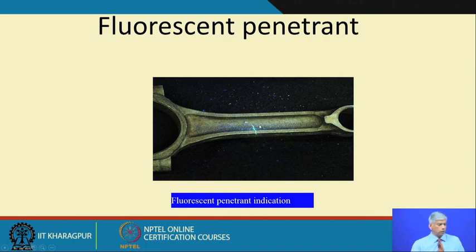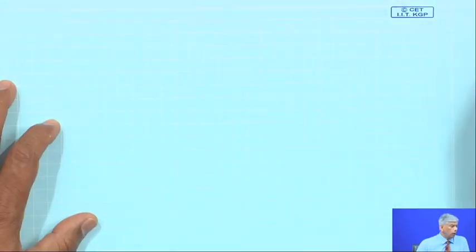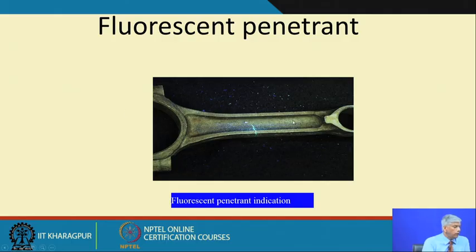So basically the component is sprayed with a dye, and then you see it under a fluorescent light. Any surface cracks will start to glow. This is a very quick way of inspecting, rather than waiting for putting it in a machine and then measuring the vibration because of this crack. It is already too late. So right in the production stage of components, maybe after a major overhaul and maintenance, people also do such checks.